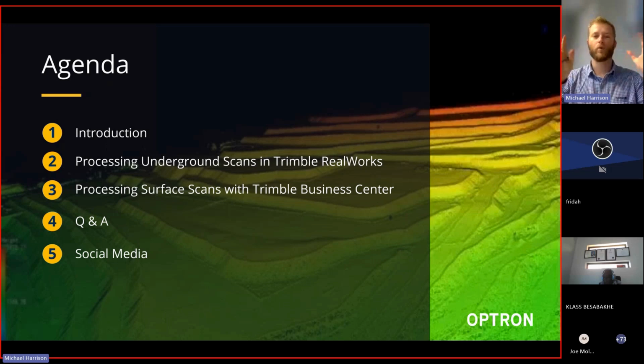It's primarily going to be the point clouds tab, taking a point cloud, classifying it into different regions, be it vegetation, ground, buildings, and then working with a feature library to use the classified point cloud regions to create deliverables such as a drawing, basically a standard CAD drawing. We won't go into the drafting aspect, which is putting a frame.